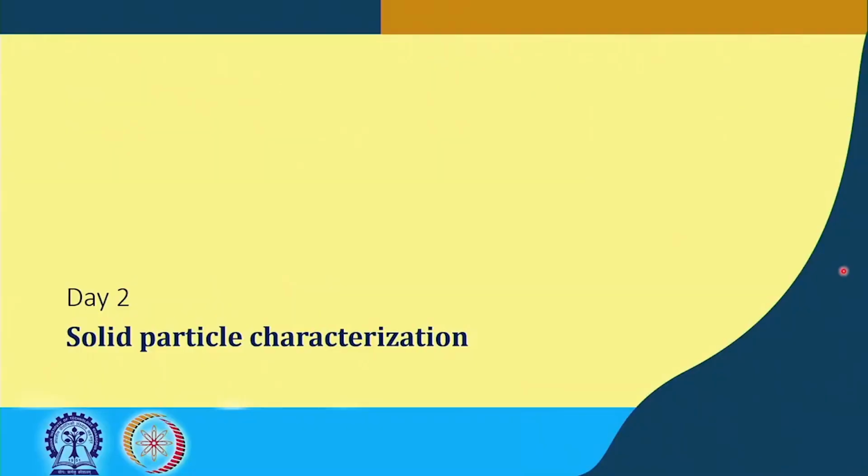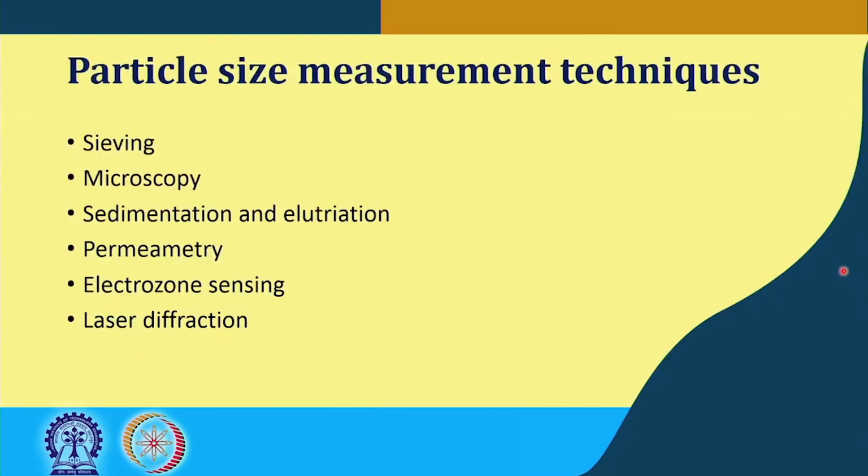Today we will go through the solid particle characterization that we started on day 1. At the end of day 1, I mentioned that particle size measurement techniques will be covered in this class. Those I mentioned the names of as well: sieving, microscopy, sedimentation and elutriation, permeametry, electrozone sensing and laser diffraction.